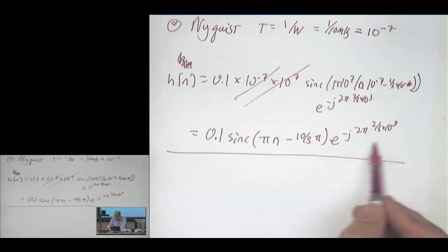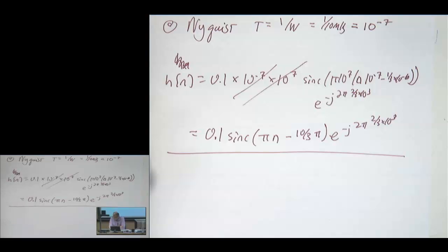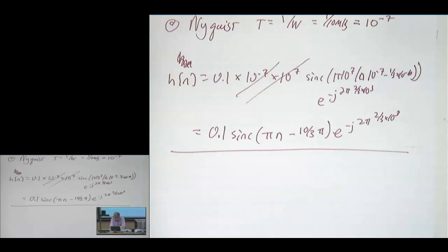So the main point here is that if you want to simulate even a very simple delayed channel, the discrete time baseband equivalent is band limited, and so you're going to get a shifted sinc function in there. And you've got a whole bunch of taps here that are all embedded in there. And this is the piece that is missing in so many references and otherwise, for reasons I know, but I care not to say at this point.